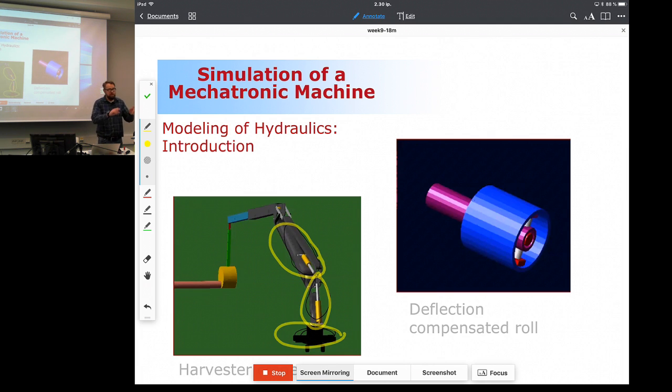So it goes in such a way that once you have a mechanical structure ready, you take an icon that is a representation of the hydraulic cylinder, you click it, and you say the cylinder is between these 2 points. Then you take another component, say a direction valve, and say here it comes. Hoses are connected from here to here, and you just define the diameter of the hoses. You define what kind of direction valve you're using, and in the background the software creates the equations that describe the hydraulics automatically, and you don't need to type anything. So that's another option. Now, how can you use this Mecha?